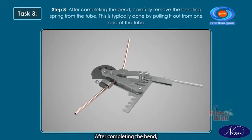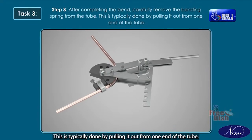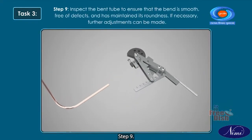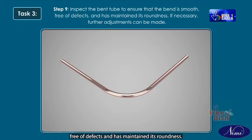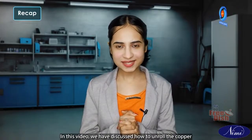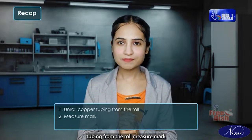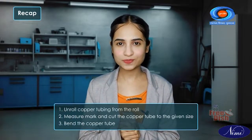Step 8. After completing the bend, carefully remove the bending spring from the tube. This is typically done by pulling it out from one end of the tube. Step 9. Inspect the bent tube to ensure that the bend is smooth, free of defects, and has maintained its roundness. If necessary, further adjustments can be made. Recap. In this video, we have discussed how to unroll the copper tubing from the roll, measure, mark, and cut the copper tube to the given size, and bend the copper tube.